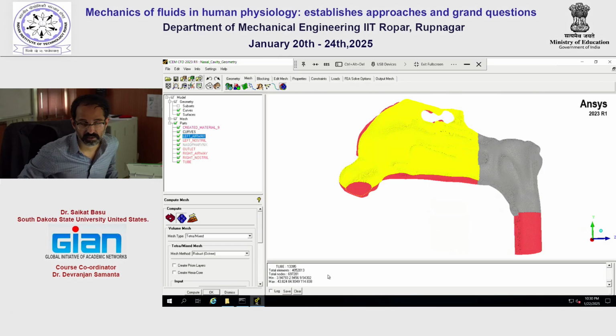if you are trying to numerically solve Navier-Stokes in as many number of elements, the simulation takes longer, right? So, for example, this simulation, if I run it, it probably takes a day at most. But the full airway simulation with the 13 million elements, the computer was not doing as well, but it took me around 11 days. So it's a function of that. So it's the time cost prohibitiveness that you need to think about. But 4 million is fine for this one.